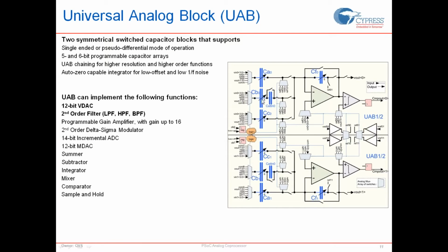If I have an amplifier and I'm switching in one phase for the input, I will have positive gain. And if I change the switching, as in change the modulation of the switching frequency, then I would have a negative gain. Meaning, if I were to sample in phase 1 on the input side and discharge in phase 2, I'd be getting a positive gain. And if I were to switch that into charging in phase 2 and discharging in phase 1, then I'll get a negative gain.